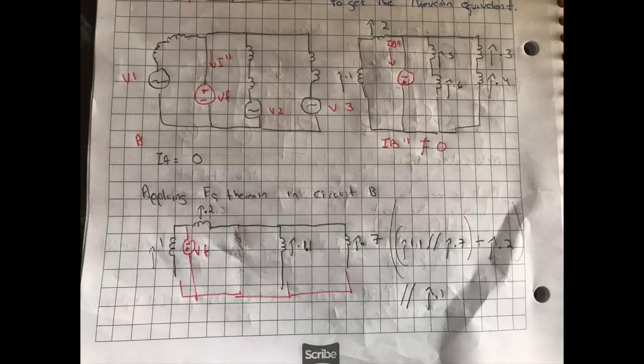So the next step is to get that current, but not in per unit, the real value, the real subtraction current. So we're using a base of 15 kilovolts for the voltage base, and for SB we assume 100 MVA.